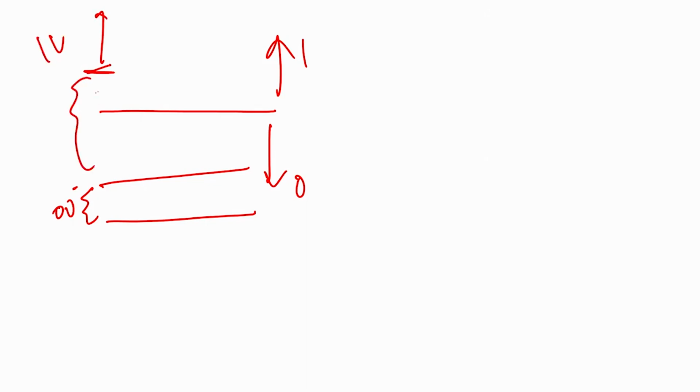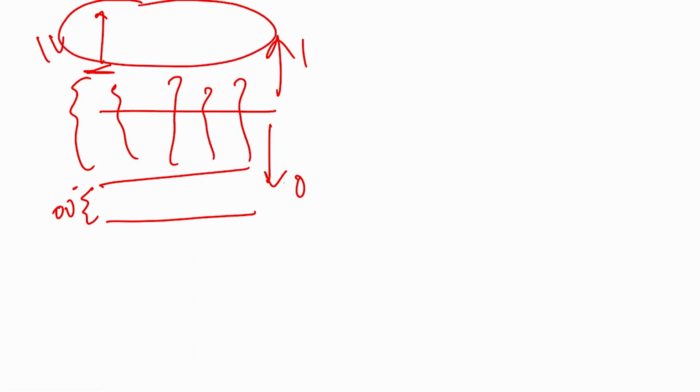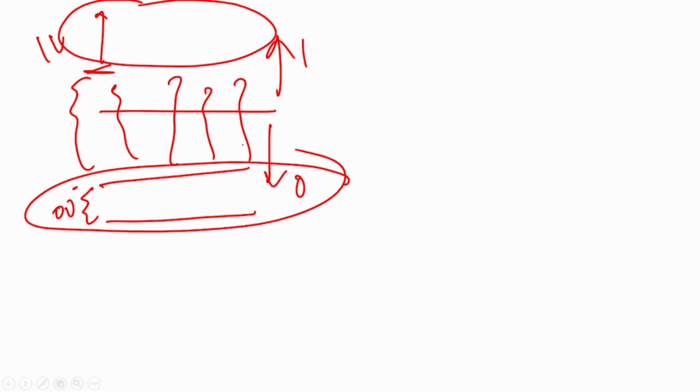This is kind of like a no man's land. Your 1 is clearly defined much above and your 0 is clearly defined much below, and this is the buffer that you keep for your noise. This is a crude way of looking at it. There are detailed discussions on this in digital design.